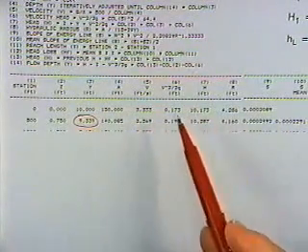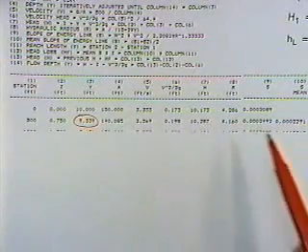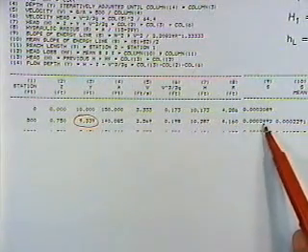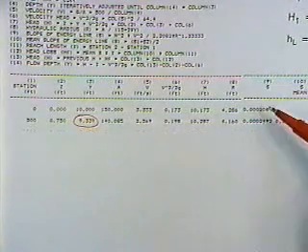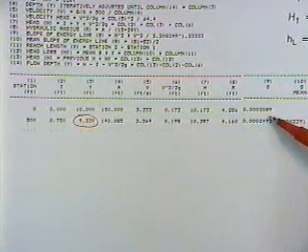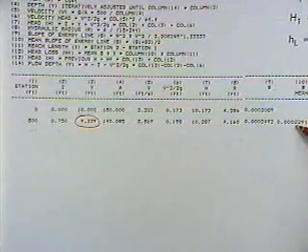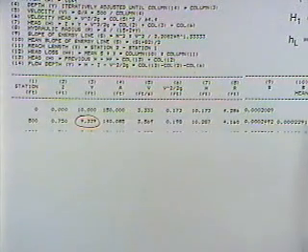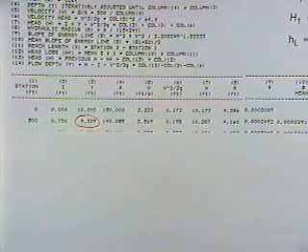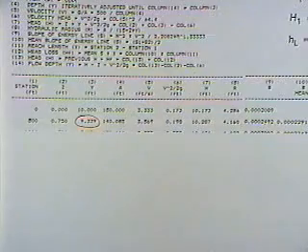I can compute the area, the velocity head, the total head, the hydraulic radius, the slope from Manning's equation, and then knowing the slope from Manning's equation at that section, and at that section I can average those two together to get an average slope, and then I use that average slope and the distance between the two sections to get a head loss term. And then I know that if I take the total head at the previous location plus the head loss, I've got to get the head at this location.